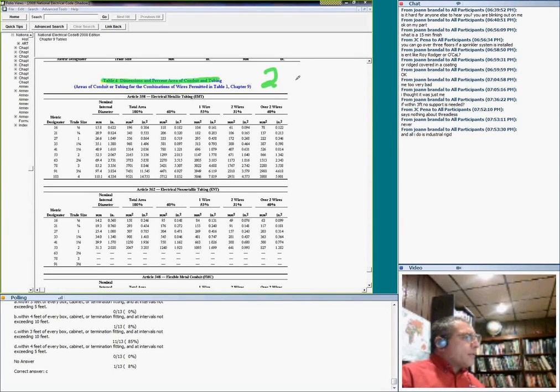For example, I have 2 conductors, number 10, a conductor number 14, and 3 conductors, number 8, all in one EMT conduit. What size conduit do I need? So that's basically it: you're going to be using Table 5. You're looking at EMT.